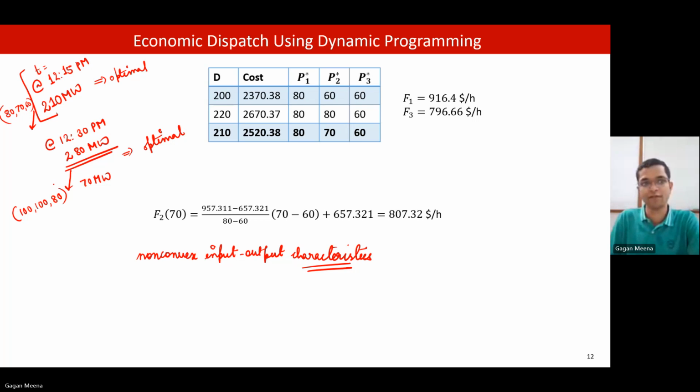However, to meet this solution, what will the AGC do? If these three generators are connected to the automatic generation control, it will say, please increase your generation, because there is an increase of load of 70 megawatts, which is divided as 20, 30 and 20 between these three generators P1, P2, P3.